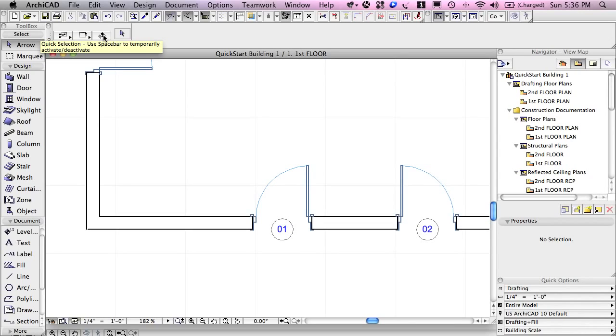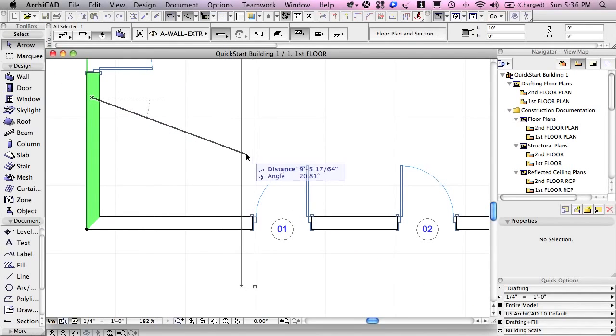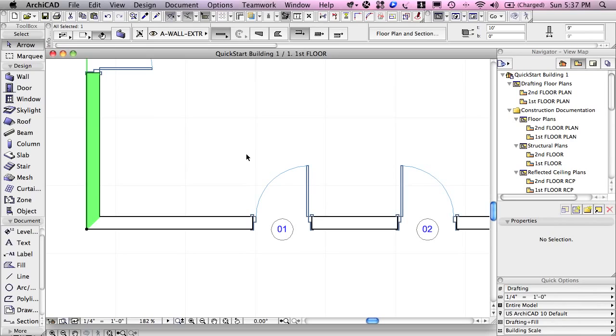So we'll be looking at this in a better context to understand it in a later module of the course, but basically having the quick selection on is convenience for most purposes, but there are times when you'll want to turn it off so that when I press down here to start to draw a box, it doesn't actually just grab this element, because in fact pressing on an element and then starting to move in one gesture is a way to drag it very quickly. So I'll just hit the escape key.